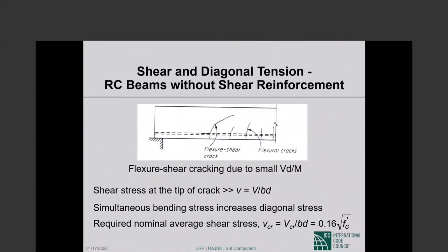Okay? What is much more common is flexural cracks open up. We know why. We have flexural tension, and at the bottom the flexural tension is horizontal. Like in the middle of the beam, the flexural tension is horizontal. We saw that from the principal stress trajectories. So the flexural cracks are vertical or near vertical, okay, as we go towards the supports. So here they're vertical. As we go near the supports, they get inclined.